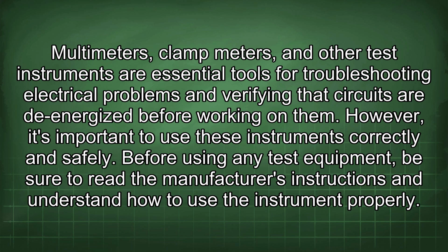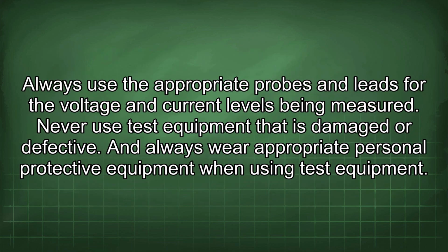Before using any test equipment, be sure to read the manufacturer's instructions and understand how to use the instrument properly. Always use the appropriate probes and leads for the voltage and current levels being measured. Never use test equipment that is damaged or defective. And always wear appropriate personal protective equipment when using test equipment.